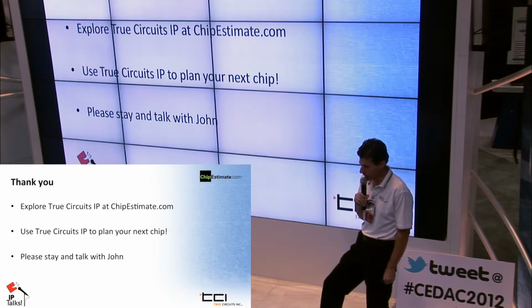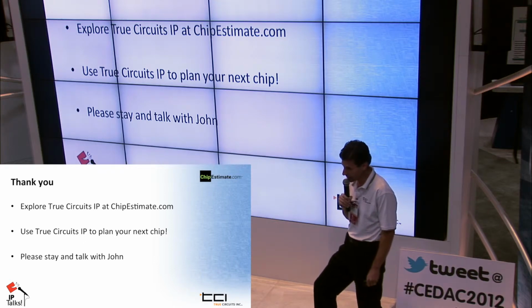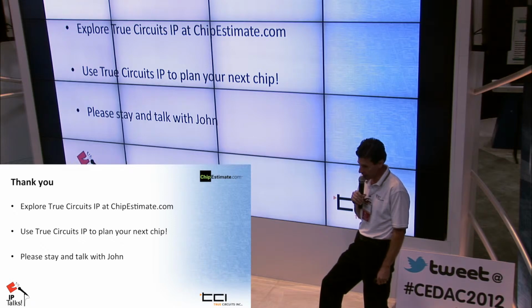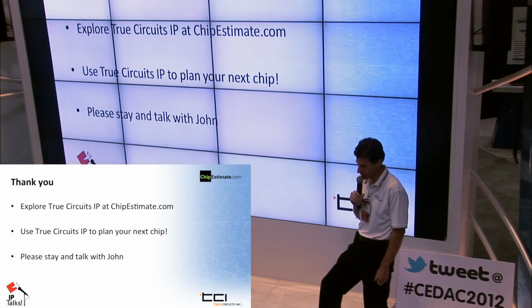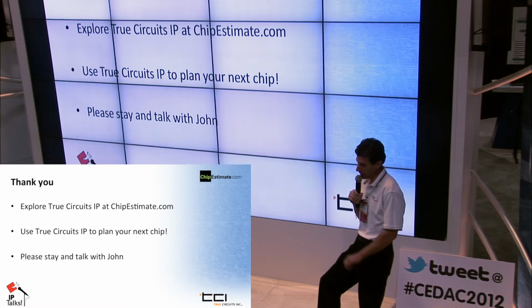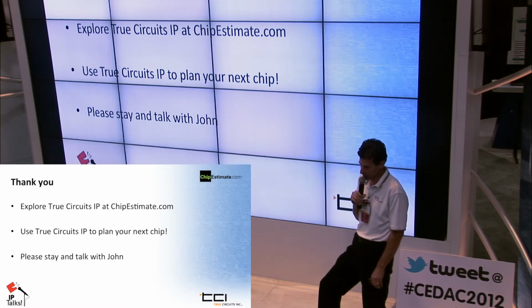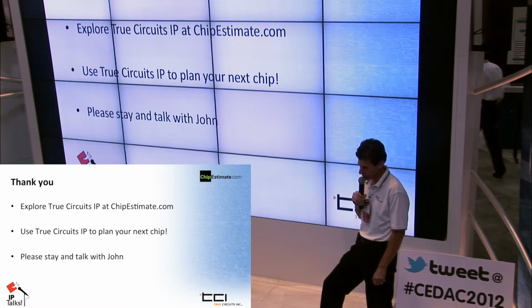And then for silicon verification, we make test chips, and we will then take that IP and verify it over all the PVT conditions, and we'll do it over a large number of samples. Because it's automated, we can get very repeatable results. We can make sure that we've done the characterization correctly, and if we're not happy with something, we can go back and recharacterize everything, until we've done it right.